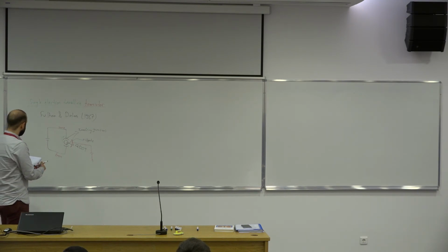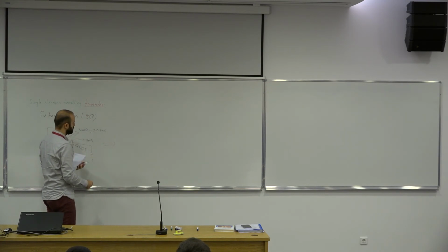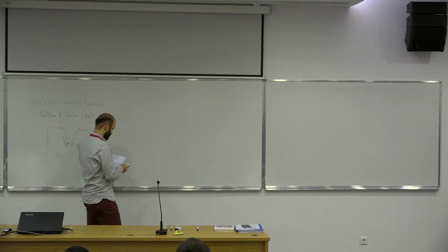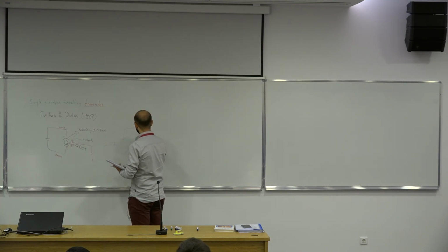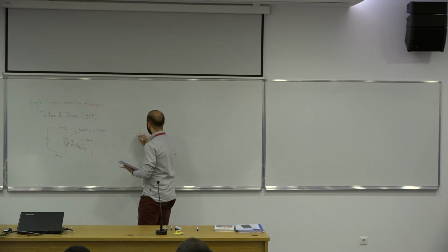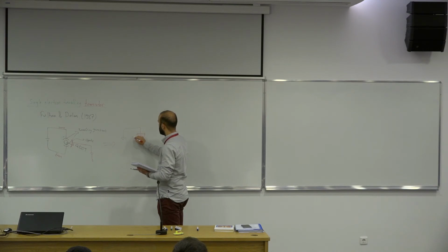The way to model this, I mean, I can draw an equivalent circuit to this, and it's not going to look too much different, but you have a leaky capacitor on one end, so we call it C1S. And then this is the dot region. And then you have another leaky capacitor, which is C1D, which goes to here.